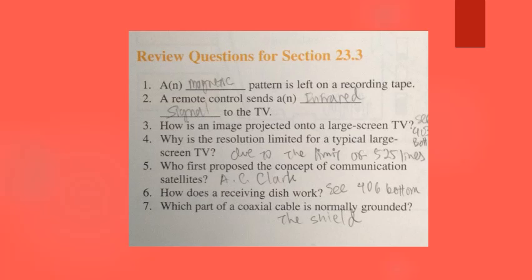6. How does a receiving dish work? The receiving dish is usually a parabolic antenna. The dish focuses the received signals from the orbiting satellite into a small area called the focal point. The feed horn then acts as a receiver on the dish on Earth, and located near the feed horn is a low noise amplifier, or LNA, that amplifies the received signal. Then the signal is fed through a piece of electrical coaxial cable to the TV receiver.